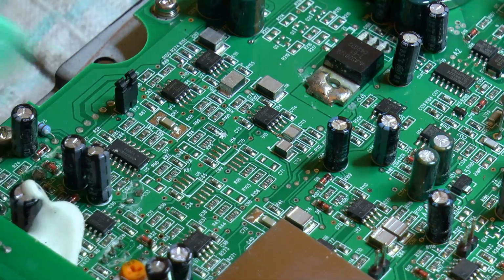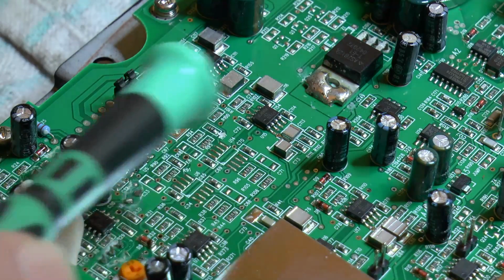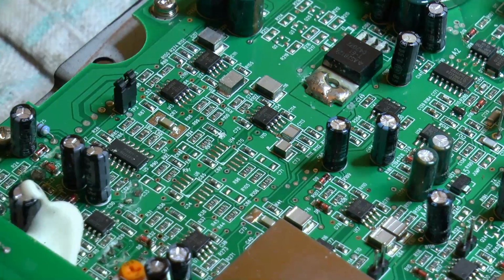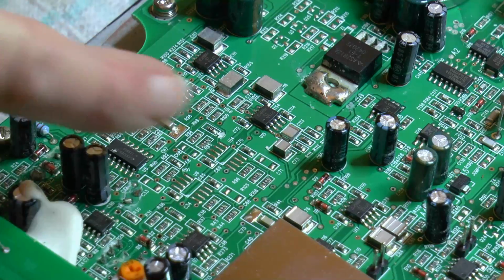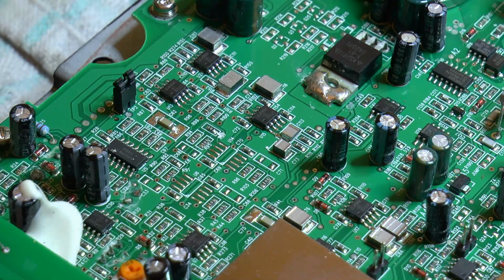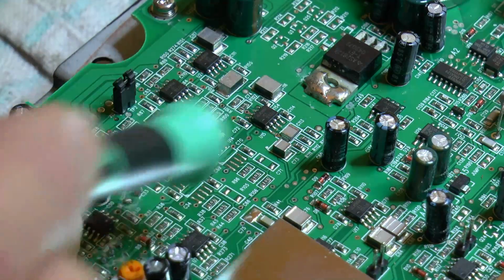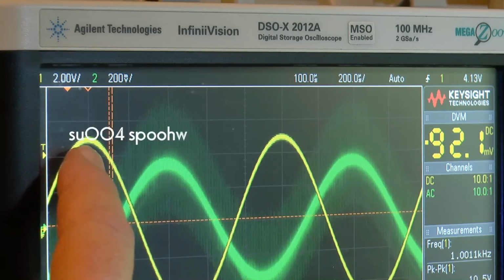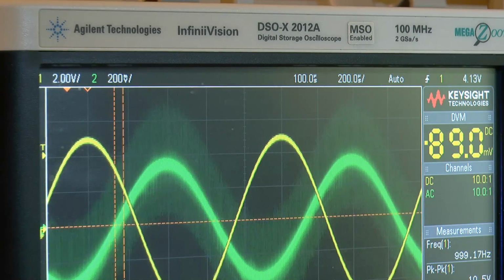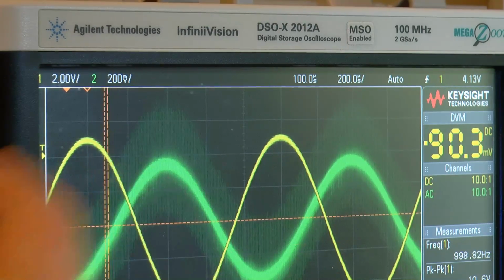So as I was saying, every amplifier I've seen, every Mackie amplifier, SRM450 V2, these 2 chips have never been populated. Some of these capacitors, I think the polystyrene, are actually over £1 each for these surface mount, or good quality ones anyway. So if they put those 2 chips back in there, give us 170 microsecond delay, that would actually, we got 200 microseconds out there roughly, so that 170 would bring that more in phase with the treble.